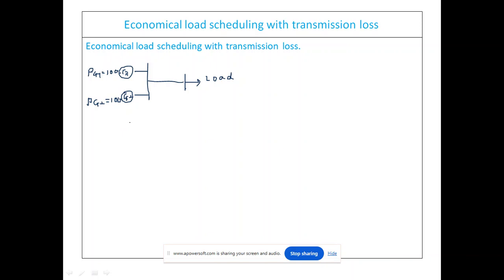So we are going to use this equation. Remember, instead of Ci I use Fi here because they have given it like that: Li dFi/dPGi equal to lambda. And remember what is Li? Li equal to 1 divided by 1 minus ∂PL/∂PGi.